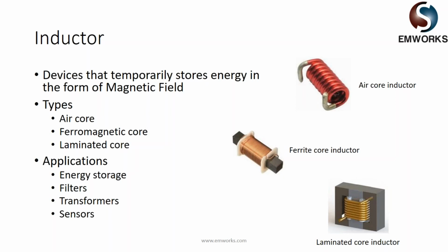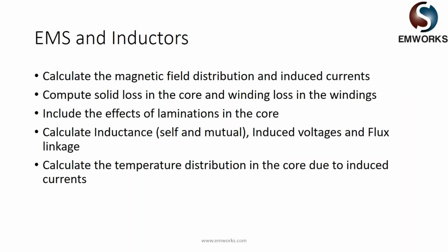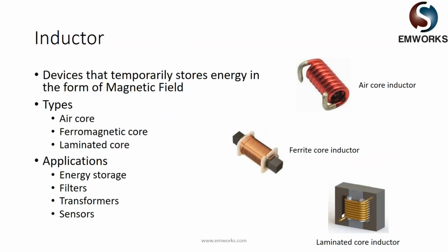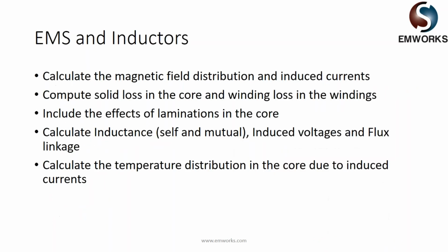Okay. The application field is quite wide, but basically anything to do with energy storage, transformers, filters, sensors, inductors play a good role here. Now, as far as EMS is concerned, how do we enable the simulation of inductors? Before I start, we can deal with all these three types of inductors that you see here. We can calculate the magnetic field distribution and the induced currents.